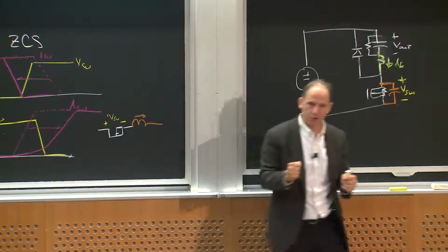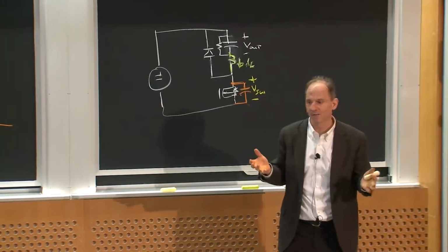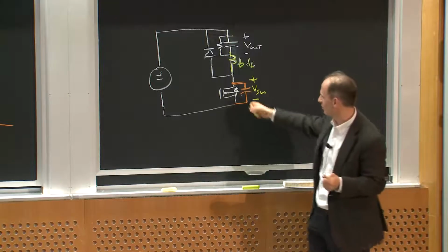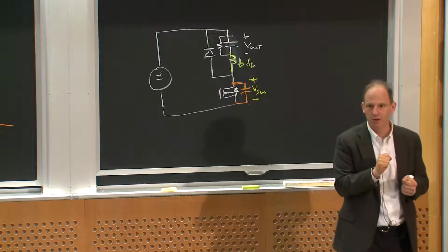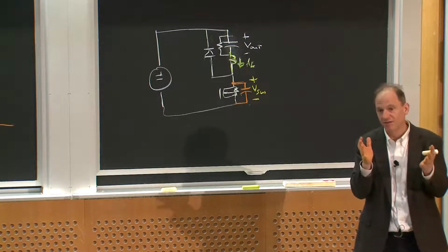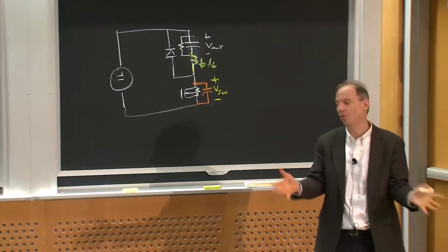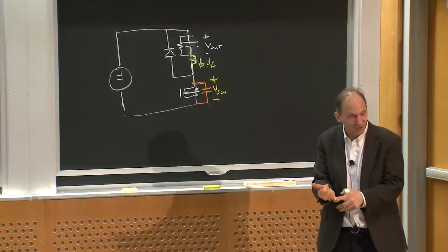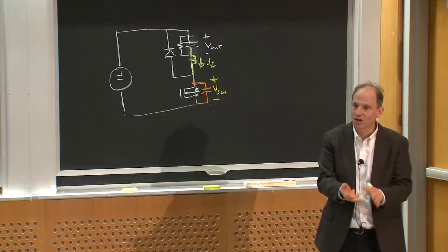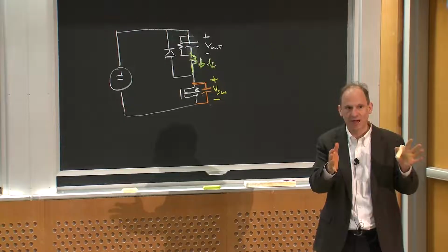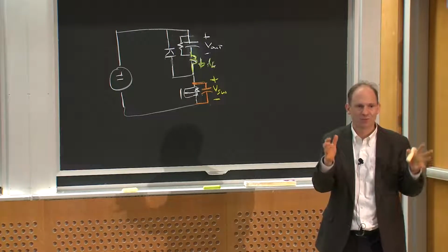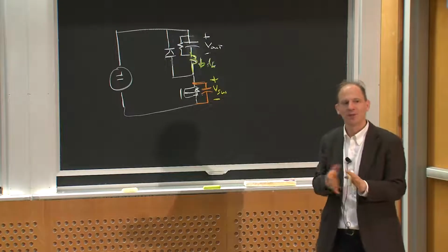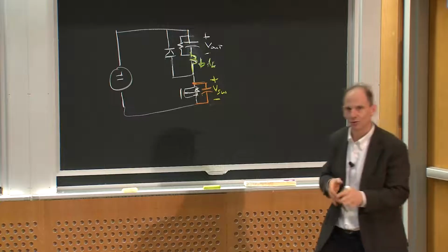To go to really high frequencies, where many people in my group design converters, we tend to focus on zero voltage switching because that lets you push up the switching frequency in the face of the device capacitance being very important. But that's a design decision. And in fact, that's why there are so many different techniques. I'm only showing you examples of these techniques. There are a lot of different ones because different devices, different applications and operating ranges all might drive you towards a different circuit that would have advantage or disadvantage, okay? And that's part of the art of designing a high-performance converter, knowing which technique to pick in what application, and what topology and what control mode to use.